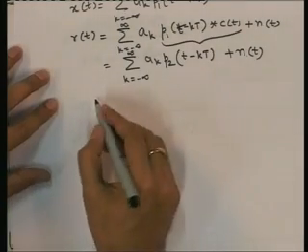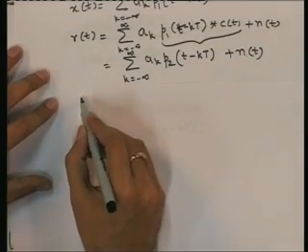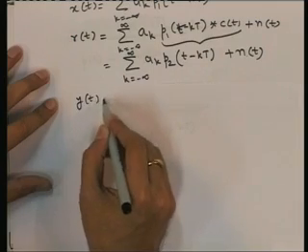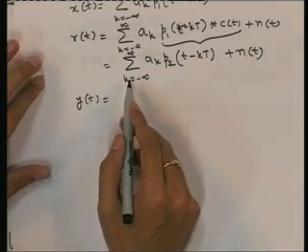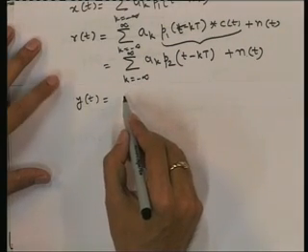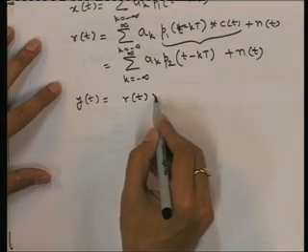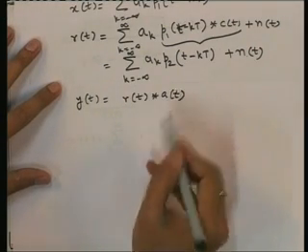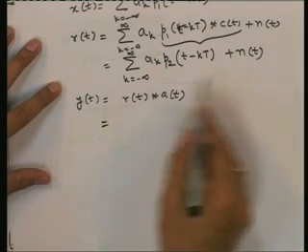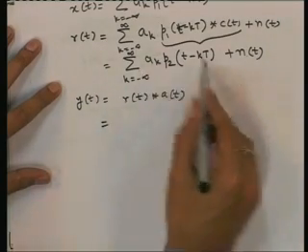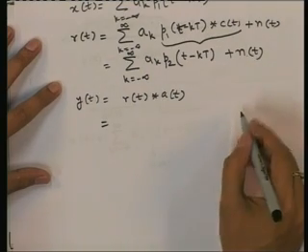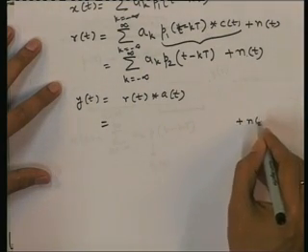So what we have here now is that y(t), which is the output of the receive filter, if r(t) is given as input, is now the convolution of r(t) with a(t). Now r(t) is this whole thing, so r(t) will be convolved with this summation and n(t). So we can write n(t) convolution r(t),